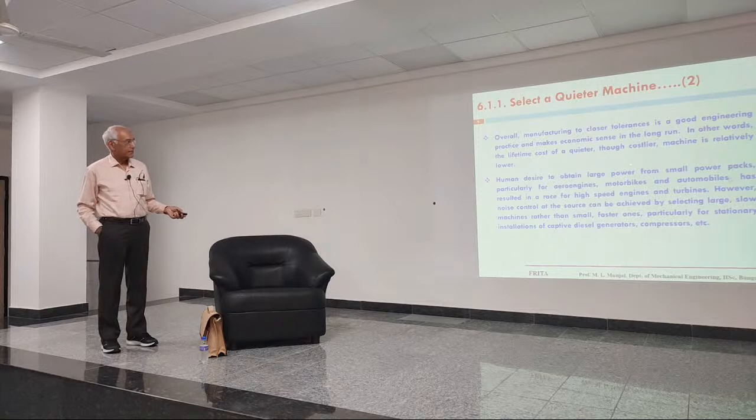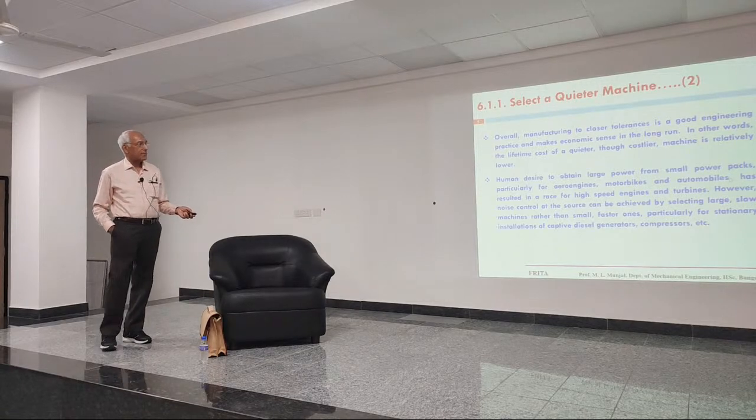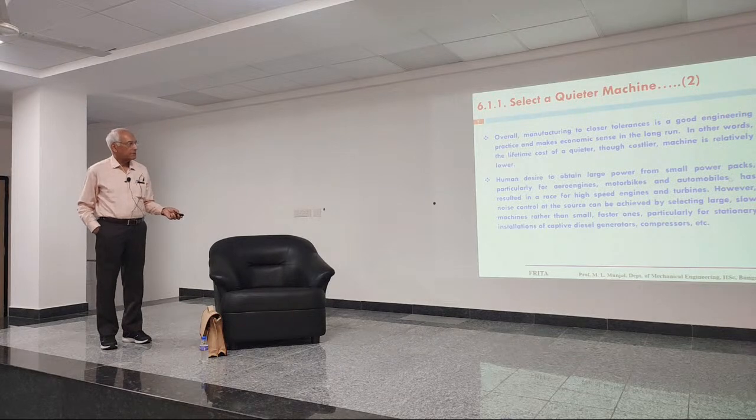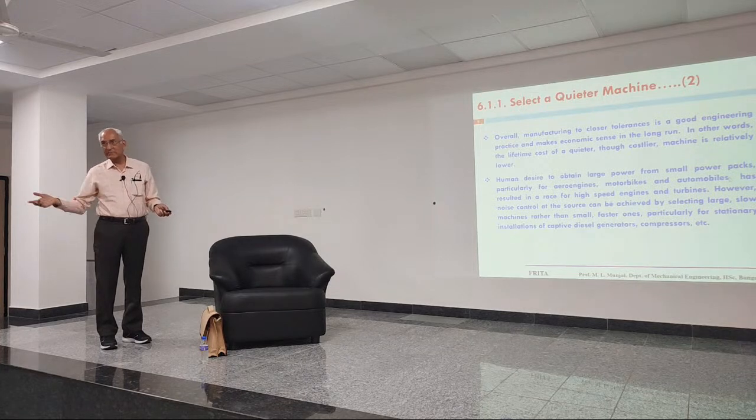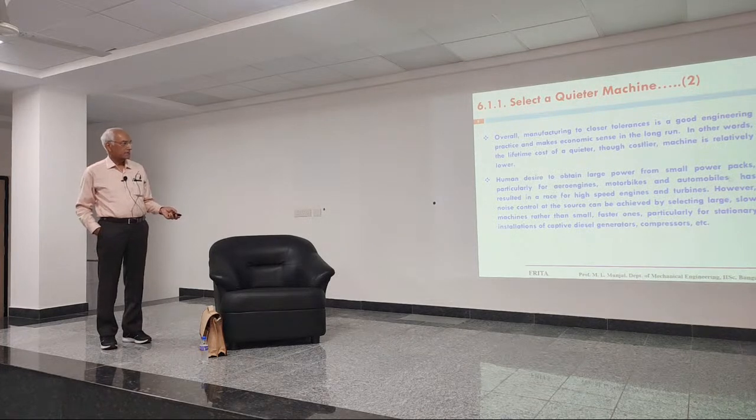Now, the human desire to obtain large power from small power packs, particularly for aerial engines, motorbikes, and automobiles, has resulted in a race for high-speed engines and turbines. However, noise control at the source can be achieved by selecting large, slow machines. Mind you, I am saying large, slow machines rather than small, faster ones, particularly for stationary installations of captive diesel generators.